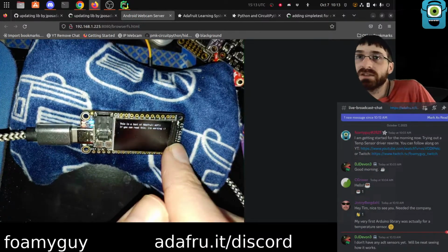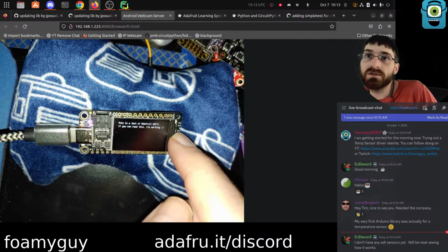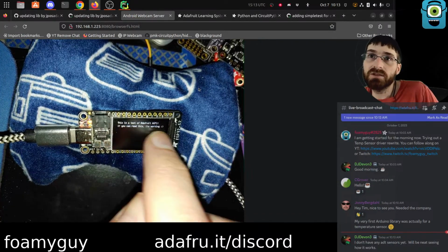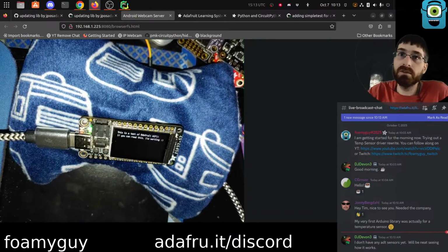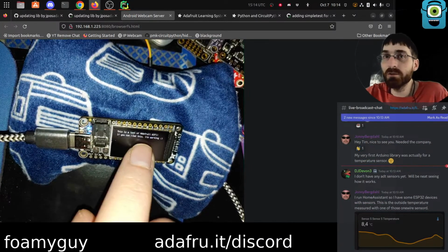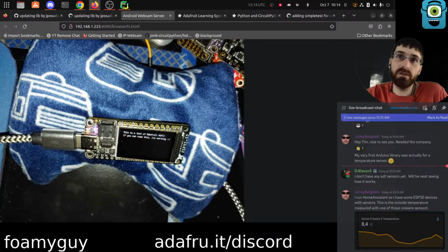As a simple test for the ESP32S2 Feather, I have made it make an HTTP GET request to the Adafruit test URL and then populate the response into a label that's been put on the display with displayio.